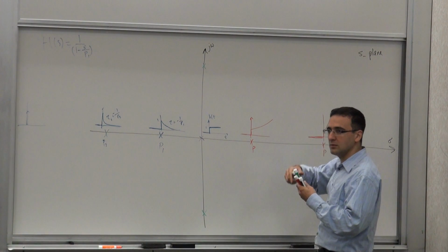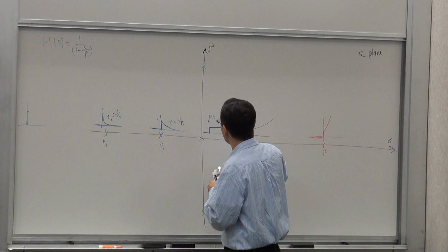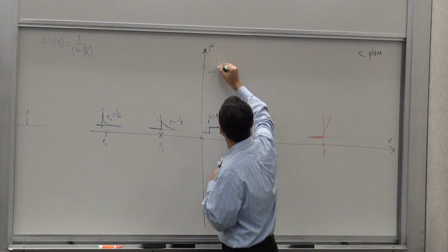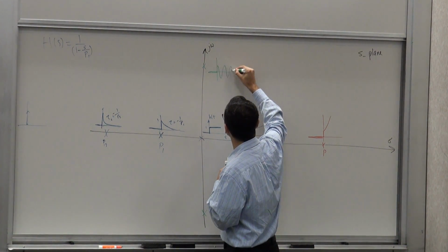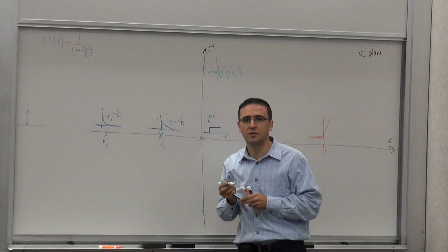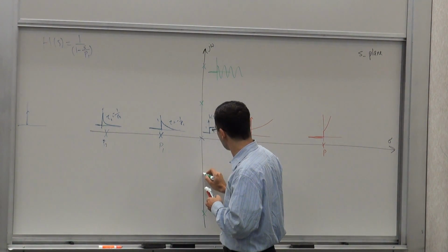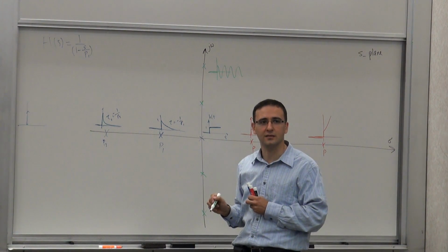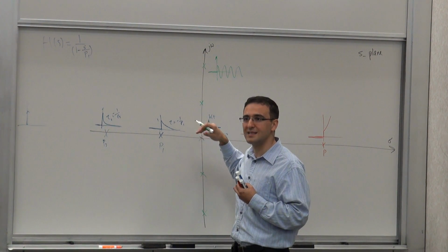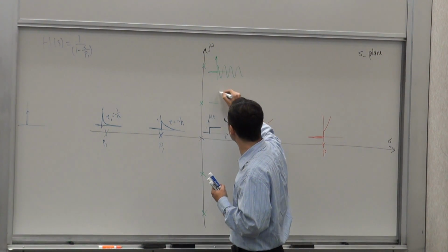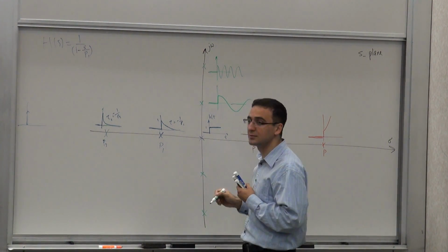So it's a sinusoidal thing, but it's not going to decay or grow. So it's going to be basically just a sinusoidal response. You go there, you will remain there. Now, what happens if these poles were closer here? Let's say there and there. What will you see there? It's a smaller frequency. So the frequency of the sinusoid should be smaller, so it should be more like this, the response of the system.